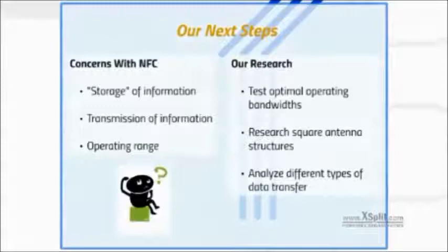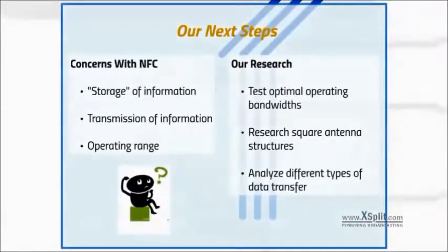Through our research, we will test different square loop antennas at a frequency of up to 20% higher than the conventional 13.56 MHz. We will also vary the input power and minimize operating distances to find a square loop antenna that is small in size but optimizes data transfer rates and uses less energy to operate. With these tests, we hope we will be able to formulate a design that, when compared to the commonly used loop antennas, is highly efficient at transferring data while keeping the information safe.